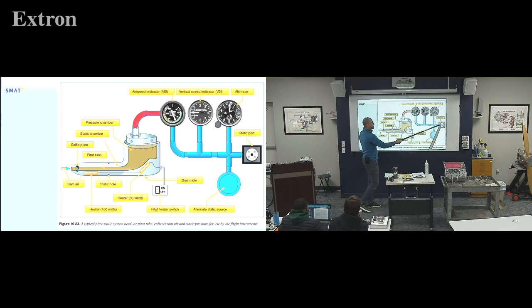And that's why it's typically the side of the aircraft. You did notice this pitot tube, maybe it has static holes on it. That's pretty uncommon. So side of the aircraft, usually there's one on each side so that if you're flying uncoordinated and slipping, they even each other out for one side or the other. So there's often more than one static port.